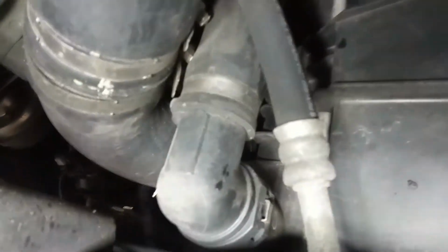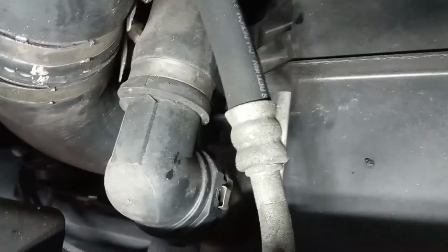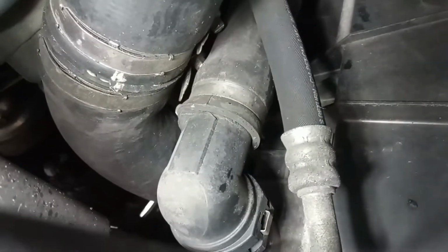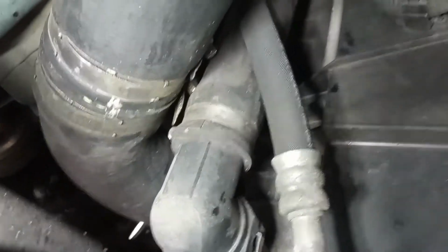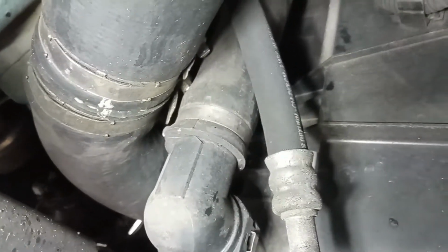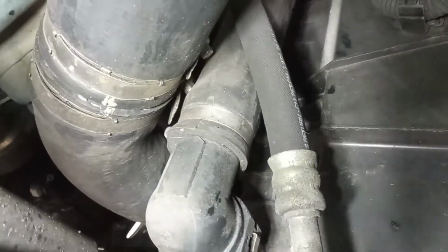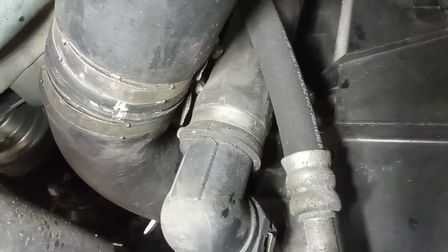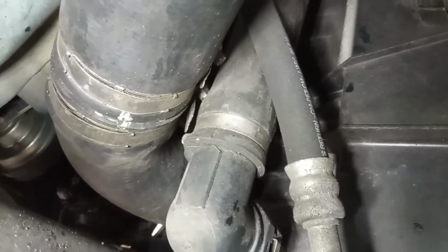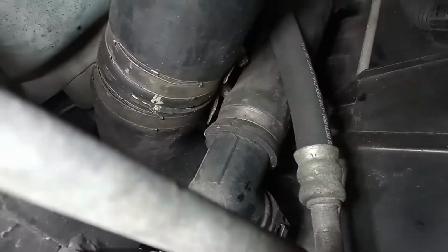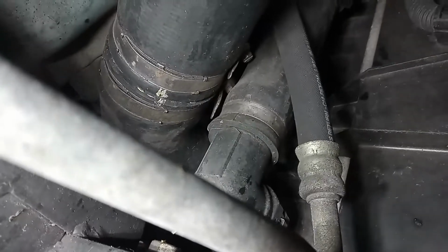But on this side, it was mended over here. Okay, it is well mended. It is correctly done. But the head of the clamp, of the second one, is biting onto the coolant pipe. Man, can't you see that when you are doing the repair? Could you not clock the clamp on other position rather than this? God, okay. So intercooler pipes are okay. I just have to clock down that clamp over there.